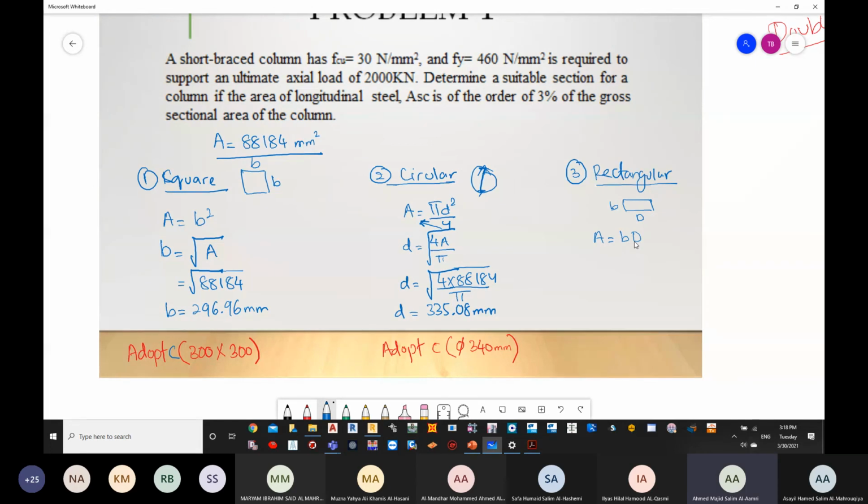thing to help me. Now, one thing to help us is that normally we use block sizes of 200. It means that normally my beams are 200, and normally my width of the column is kept to be 200, so it cannot go outside, or it shouldn't go outside the wall.